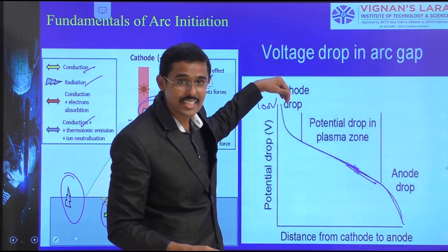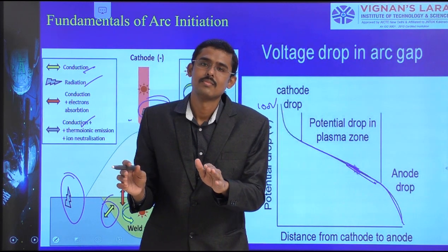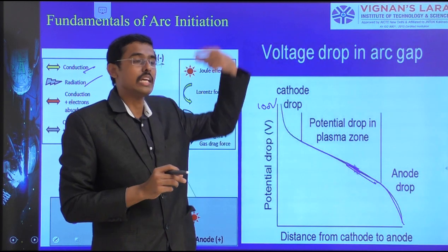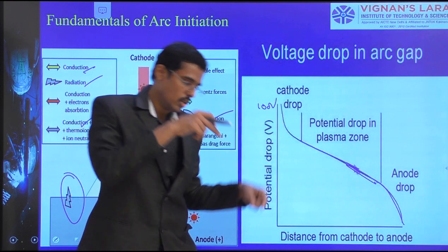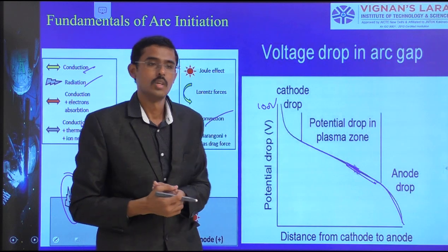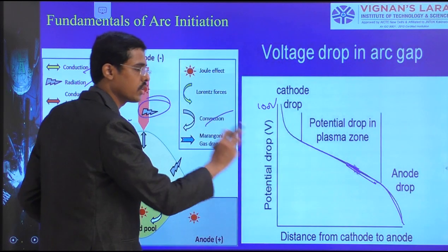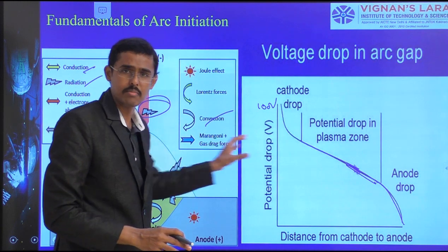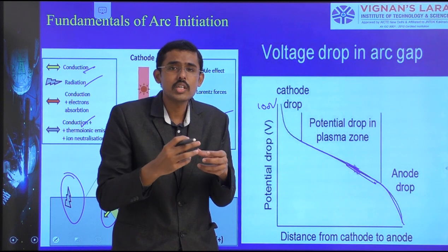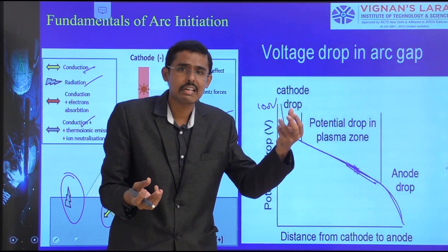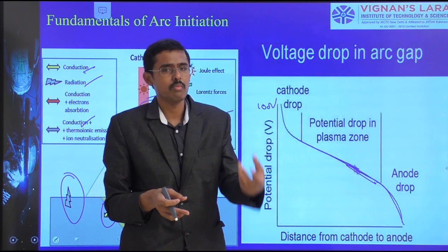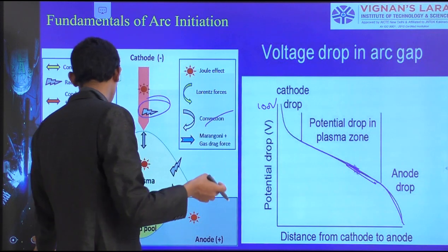So this voltage gets dropped, though it should not drop. We should keep giving more voltage for successful reaching of the electron released at the cathode spot to the anode spot. Then the heat generated reaches the workpiece. So this is what is happening. At the initial stage we are pushing out. When it comes to the atmospheric, gaseous zone, collisions automatically happen between the gaseous molecules and the released electrons. Therefore, heat is generated, and this heat melts the electrode, which is automatically deposited, welded. So that is what. Okay.